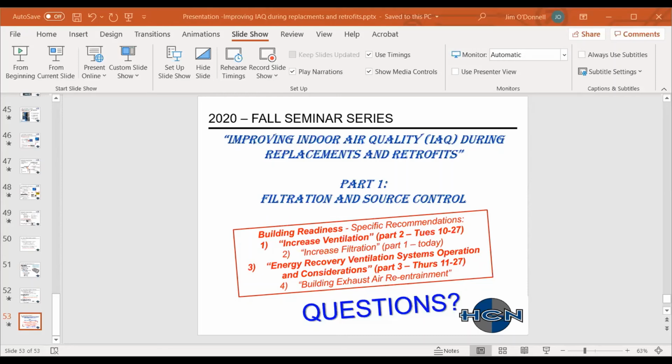Right. The second follow-up question, by the same person: does that mean you have to resize air handling units and oversize the cabinets to achieve 250 feet per minute? I would say not to do that. The GPS product is sized per CFM. I'd say that's a waste of money; you're going to have much larger equipment, you're going to need more space, as well as a higher first cost.